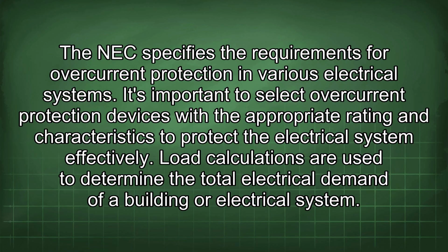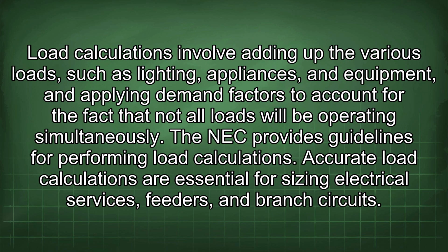Load calculations are used to determine the total electrical demand of a building or electrical system. Load calculations involve adding up the various loads, such as lighting, appliances, and equipment, and applying demand factors to account for the fact that not all loads will be operating simultaneously. The NEC provides guidelines for performing load calculations. Accurate load calculations are essential for sizing electrical services, feeders, and branch circuits.